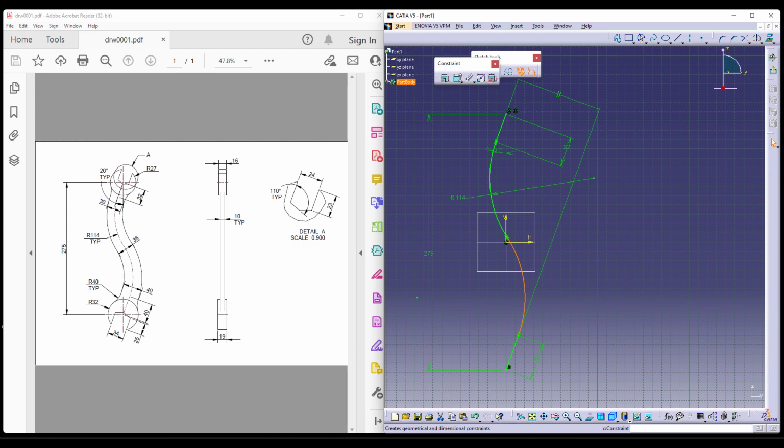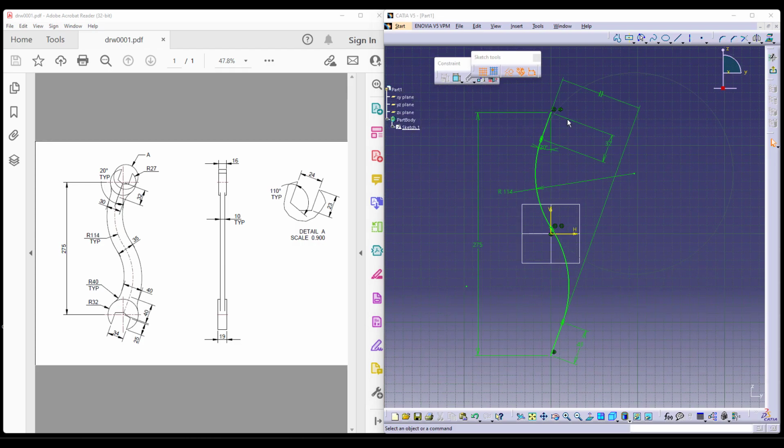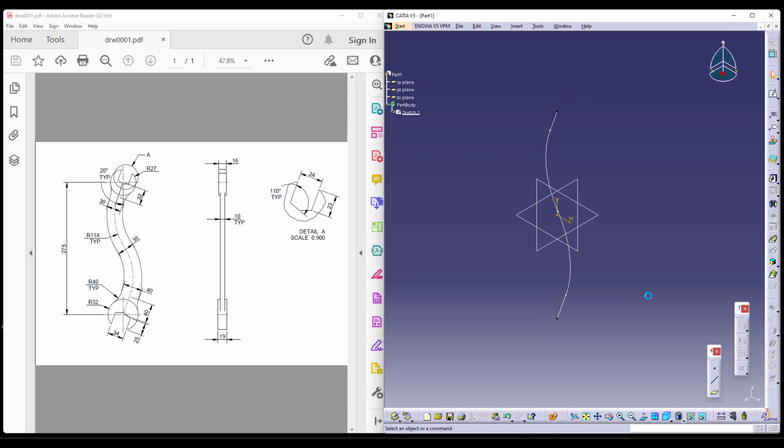Now the radii of this arc will be auto-constrained with respect to this. So let me try to delete since they are overly constrained. Now the variation of the paths are at the beginning, the center as well as at the end. Now, the variation will be in the software, it will be at this location and this location at this location. So, we require 3 different planes to maintain the profile.